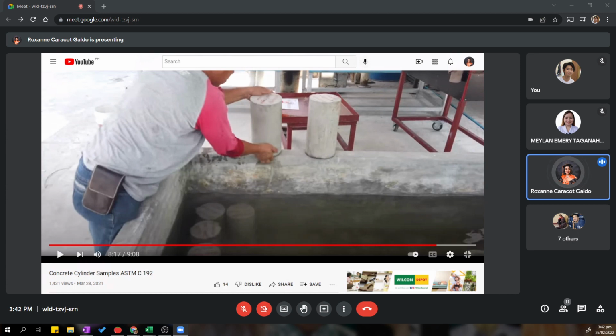And number two is to mimic the worst site condition. Usually, the worst condition the pavement would undergo is full submersion in water, or water intrusion. That is very stressful and prone to damage, when your pavement is submerged in water, especially on roads with poorly designed drainage.